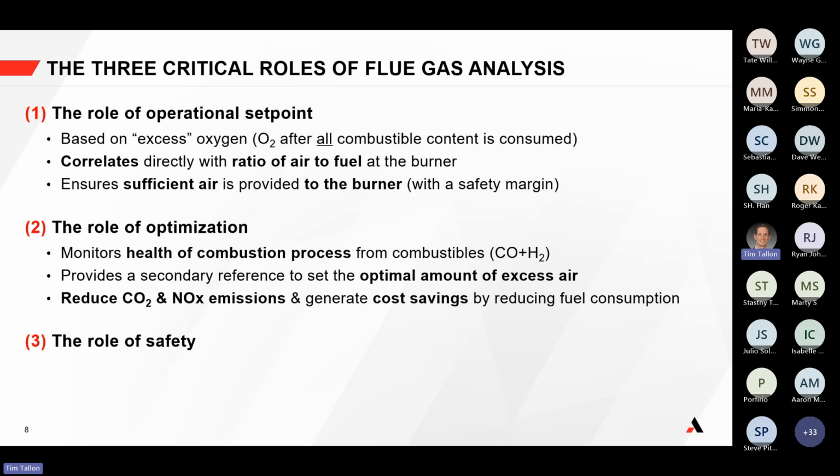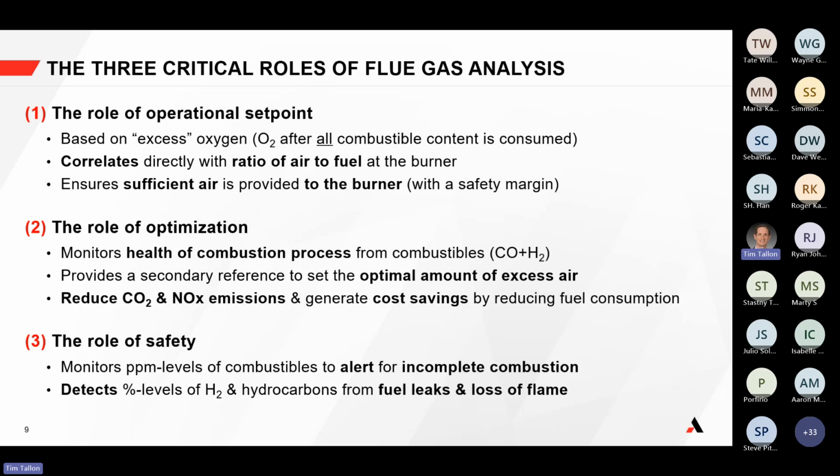Now, the third reason why an operator would even consider flue gas analysis is the role of safety. And safety is probably the most important one, but just to give it emphasis, I mentioned safety margin up here at the burner. That's certainly important to make sure that you're above stoichiometric conditions, make sure you're above fuel-rich conditions.